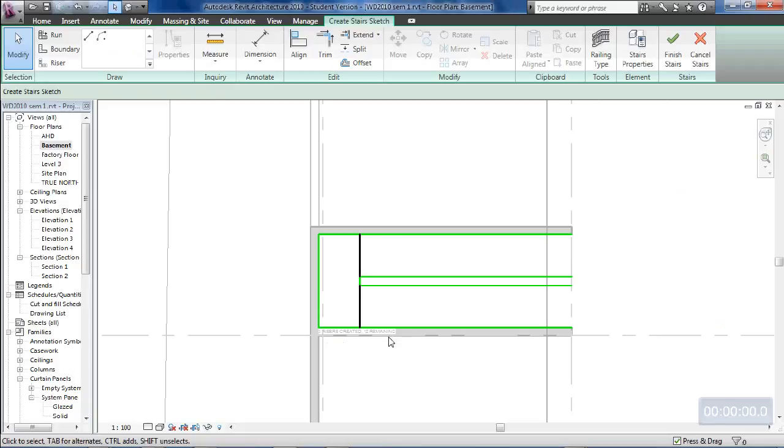Now it's most important that this drawing is done neatly, without any lines on top of lines to overlap, and that all of your boundaries intersect at corners, etc. The other thing you will need to do is split your boundaries at the landings. So at that point, and then at that point. That's because a stringer, if this was a stringer, cannot be a straight line from the bottom of the stairs here up to the top of that landing. It has to slope from that point to that point, and then change slope, actually flatten out across the landing. So that's the concept there.